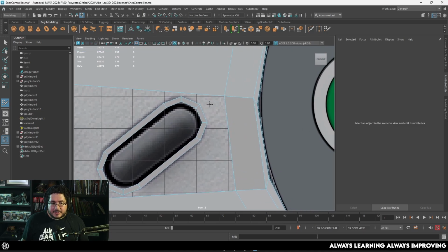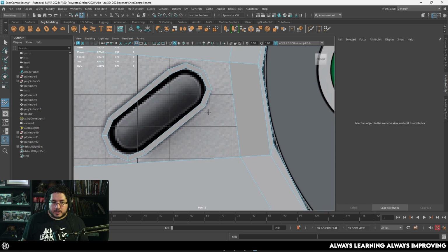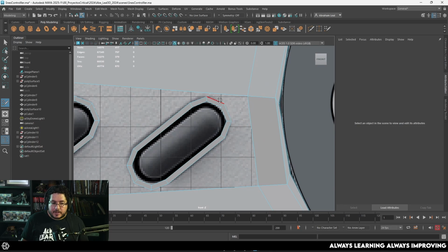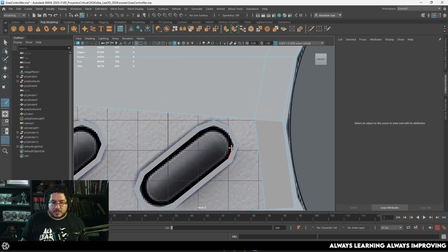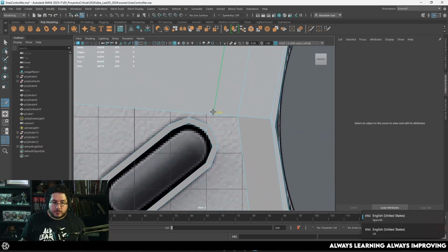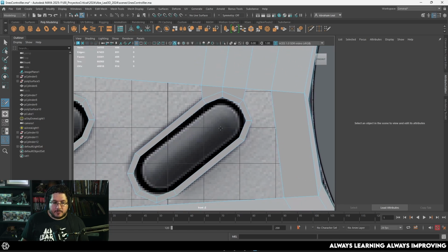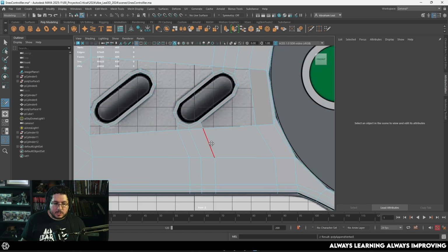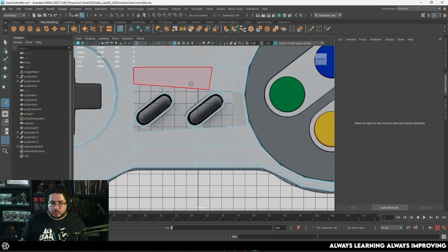Now, over on this side, what we can do is try to find how to create a little bit of a loop trick. We don't want to just add a bunch of crazy lines. We already said that was not going to work. So we need to find a way of reducing the amount of loops that we have right here and merging them with these flat areas over here that are not going to affect us too much. So for instance, if I add one edge loop right there and one right there, this one just steps right there, and that's fine. And same for this one right here. And we can do the same thing on the bottom part right here. We just add a couple of edge loops, and these edge loops are just going to go down exactly as what we want, which is this thing right here.